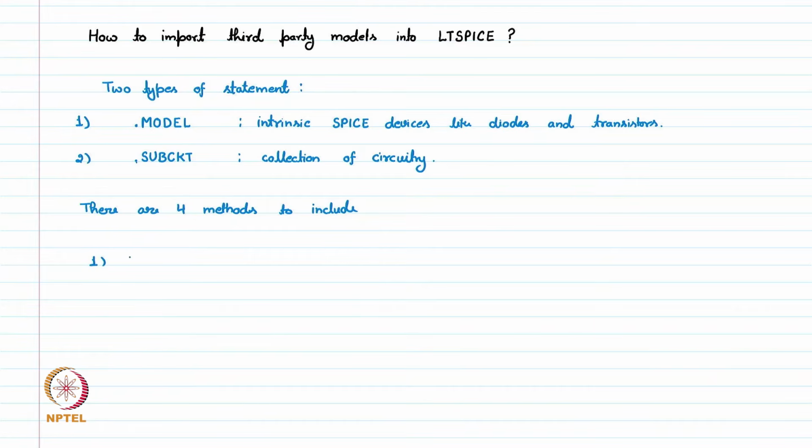And now there are four methods to do the same thing. The first one is copy and paste. The second method is to use dot include, or in short, we can write dot inc. This is the statement. The third is use dot lib.